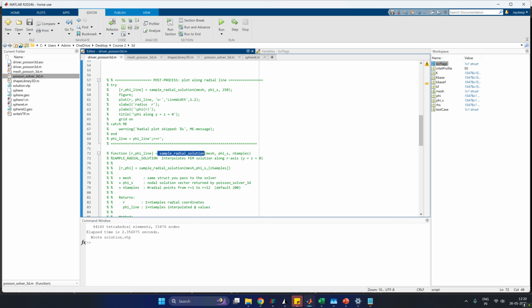And at each of those nodes, you basically interpolate the solution. For that, first you have to again go to the element to node connectivity list, or rather the x coordinate. I mean the node, you have to extract the x values of your xyz values of your nodes, and then use your element to node connectivity.